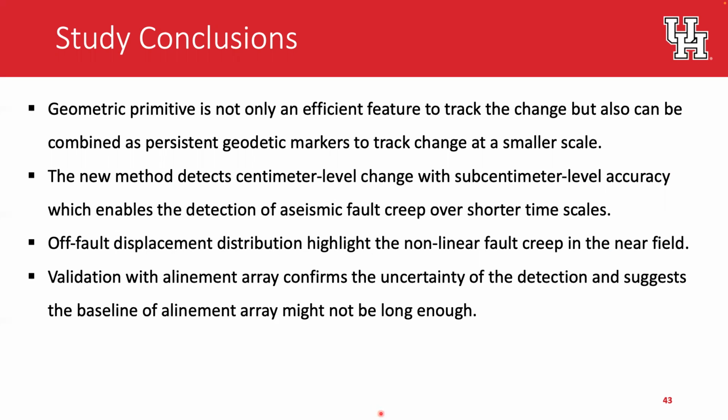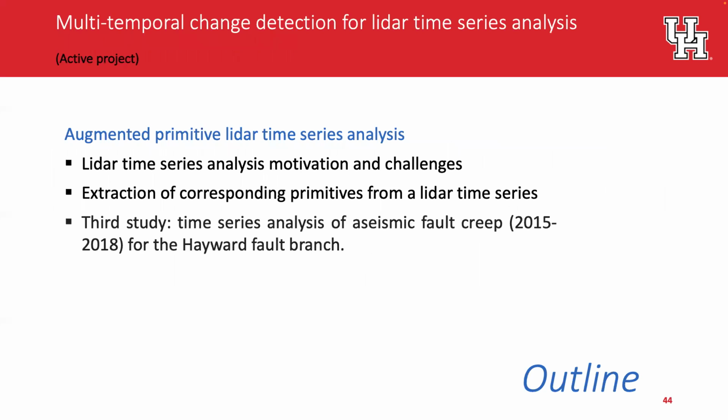Very briefly, the next piece of this that hasn't been published yet, but that is part of Sean's dissertation is, well, that's just deformation between 2 epochs, 2017 minus 2015. But I mentioned we've been observing this for 8 years. Well, what is often done in InSAR processing is you stack a whole bunch of interferograms because as you keep stacking, you reduce some of the atmospheric noise.